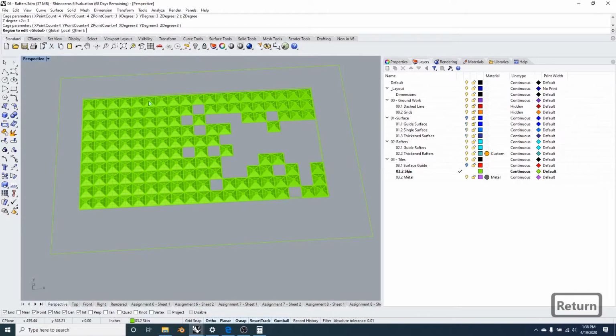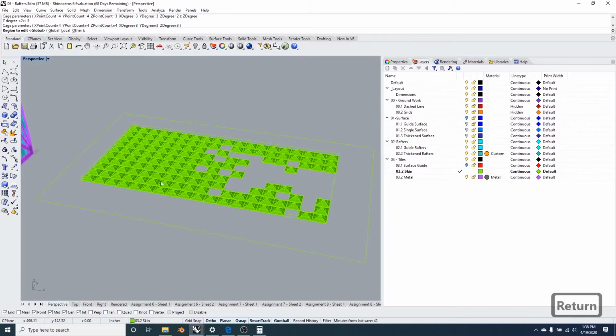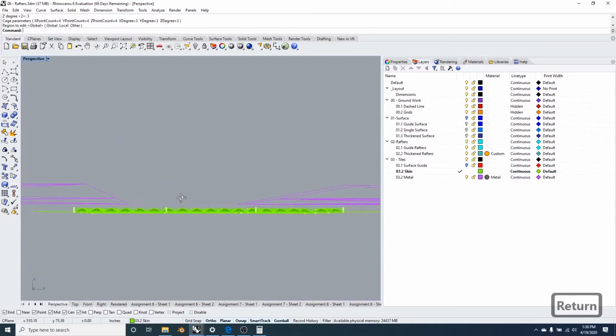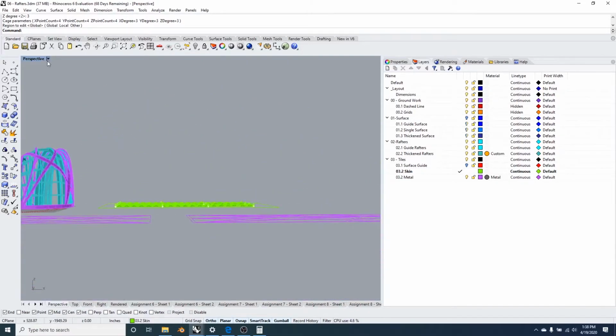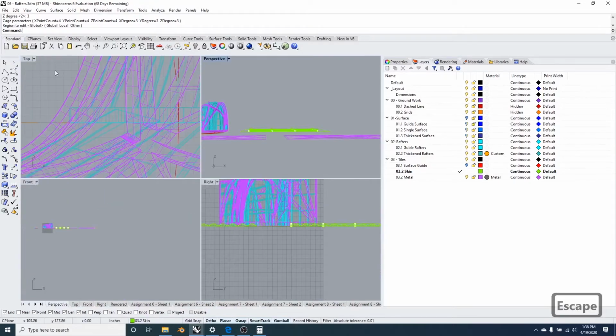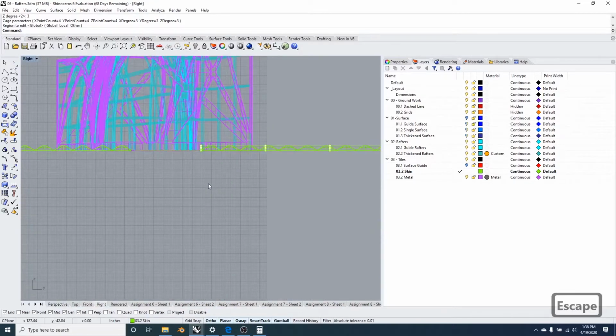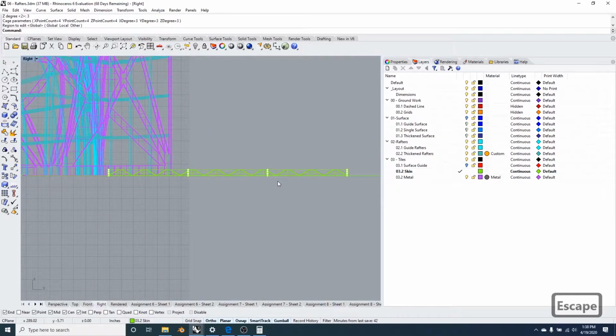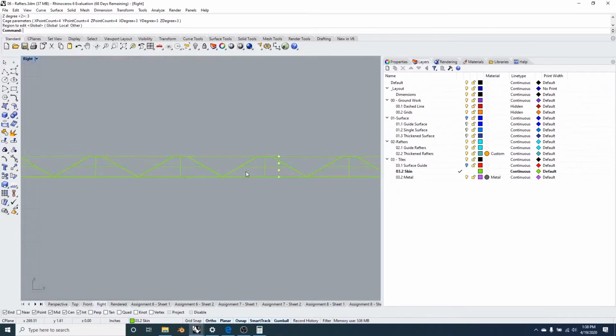And then region to edit, this is just asking you, this is pretty much running this show object control points, which, since we are on the bounding box that we are currently doing, is going to turn on the one that we just specified. So if you hit enter, it should just show you the points. Okay, so we got the points, and this works better if you switch to an orthographic left or right or front. You can see that we have all the points in there.